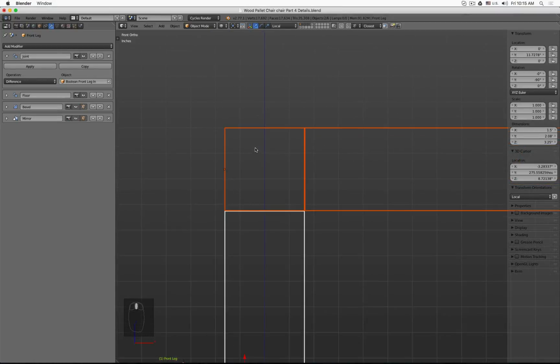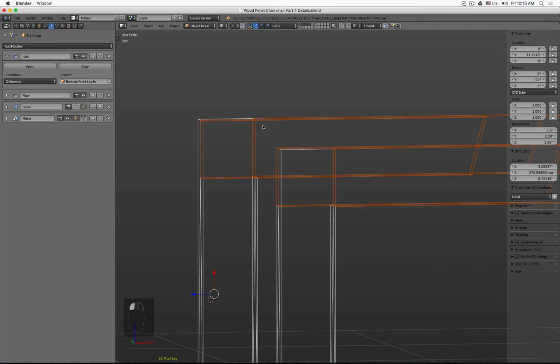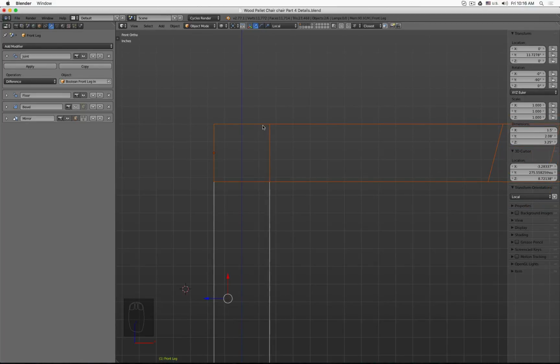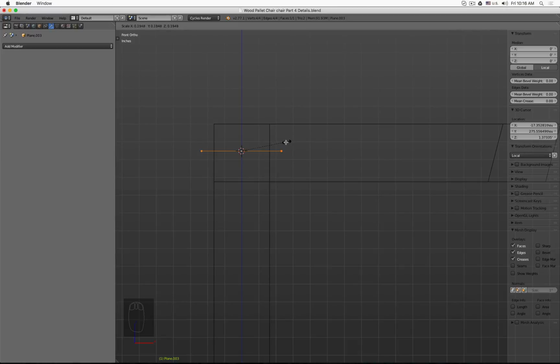So this is actually quite easy. First, with all these selected, hold the Alt key and then we turn off the bevel so we have perfect snap targets. And then we just position the 3D cursor roughly here, Shift A, make a plane, and then this plane we can scale down in edit mode. And in my case, along the x-axis, I rotate it by 90 degrees.